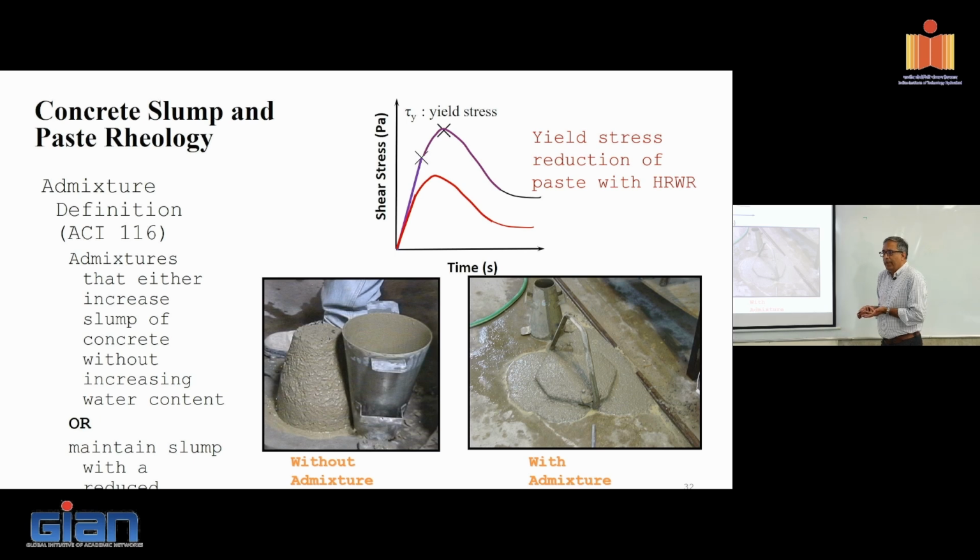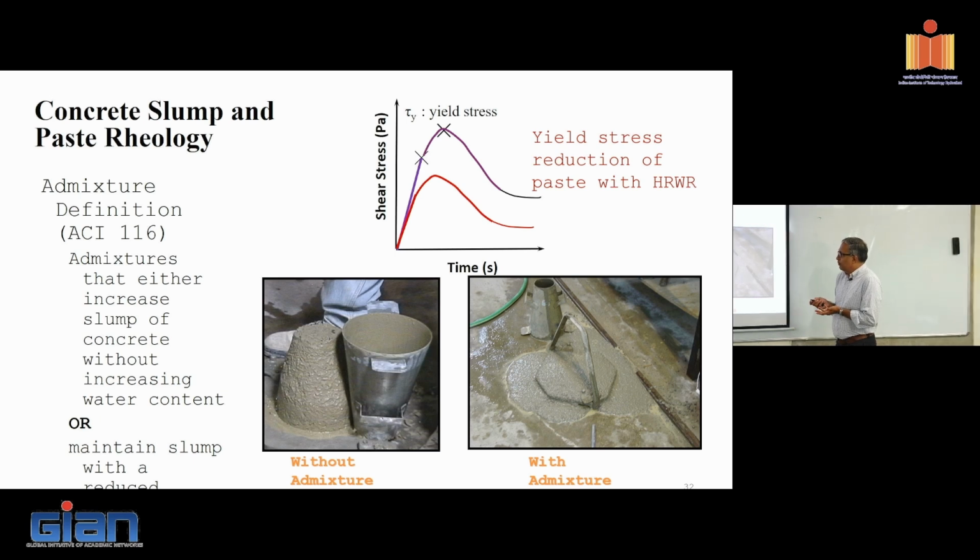It's not going to slump, right? So when I lift the slump cone, basically it sits in the original shape. How is it able to keep the shape? Between the aggregate, the paste has such a high yield stress that it doesn't shear off. It's going to hold on to the aggregates in position. So you end up with a nice stiff concrete. How do I get this thing to flow? I've already pressed all my levers.